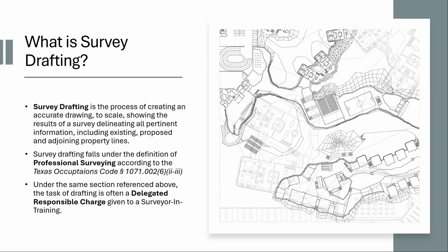That's where maybe you're going to have to say, hey, I'm trying to draw this, but I don't have equal distributions of points, or I have a rough idea of what this terrain looks like, but I don't have tight enough points around maybe some of my cliff faces. And you can kind of see an idea of what I'm talking about with cliff faces here on this tint model. It's representing the topography. So these are real tight. This is showing there's a steep change in height, with a high point here, down low here, and this is a bit gentler of a slope, and this being a bit more medium. That's the kind of stuff that is going to be important to capture.